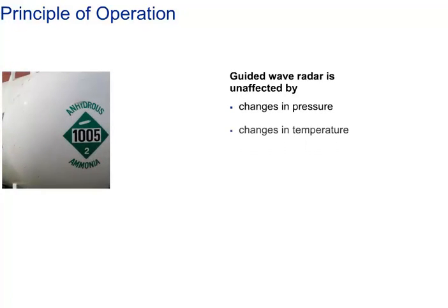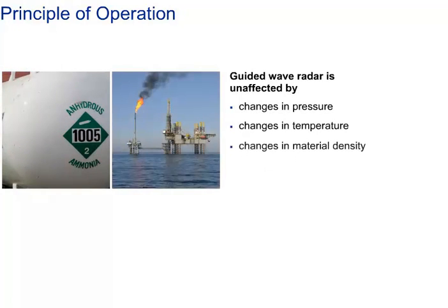As you've already learned, guided wave radar uses dielectric constant as the measurement variable. So what influence do the other common process variables have on guided wave radar? Guided wave radar is unaffected by the following variables: changes in pressure, changes in temperature, changes in material density.